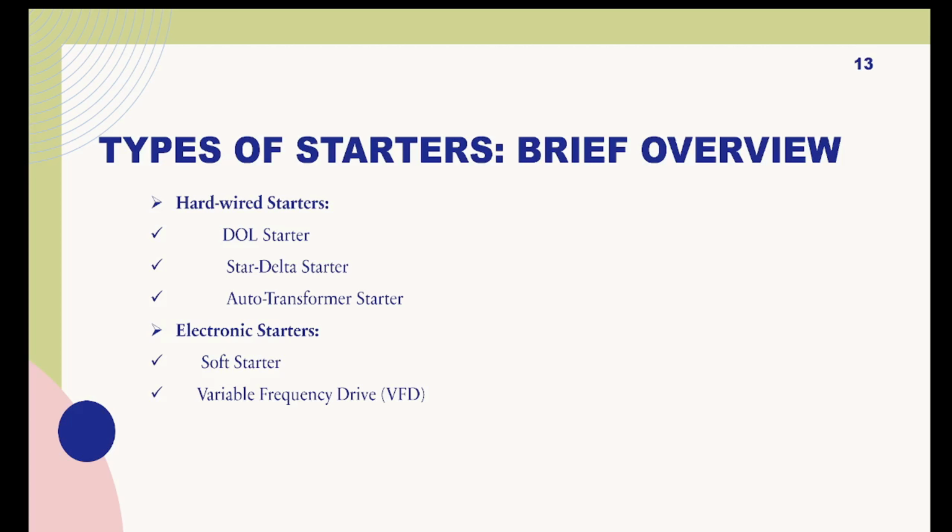Electronic starters. Soft starter. A soft starter gradually increases the motor's voltage, ensuring a smooth start with limited current. Variable frequency drive, VFD. A VFD provides even more control by adjusting both the voltage and frequency, allowing for precise control of the motor's speed and torque.